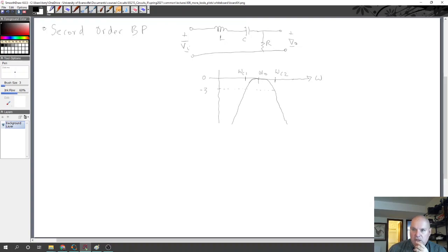And so this is going to be the transfer function or frequency response of this particular circuit in a Bode magnitude plot. In a linear plot, it's actually going to look more like this, where this is omega 0. It would have a peak response of 1 and go to 0 as a function of omega.